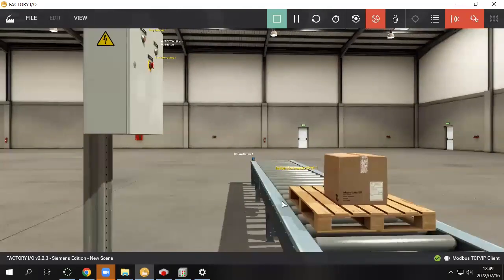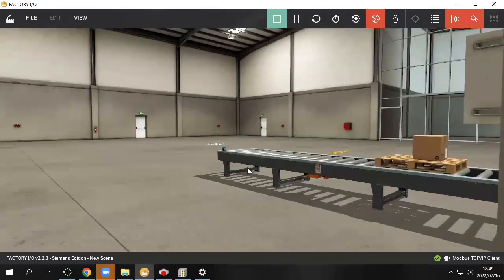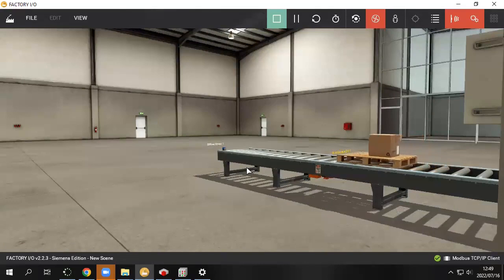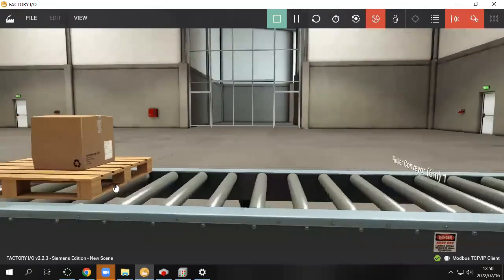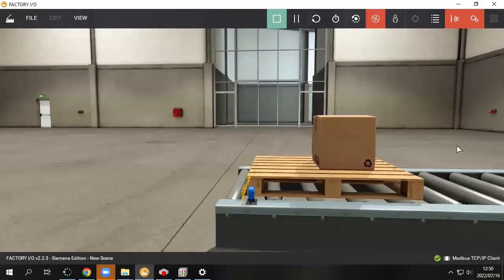Right. So now, at first, what did it do? It fell. So we don't want it to fall. Yeah, this is why we're having this. Yes, stop. So now, it stops immediately. Maybe after a few moments, you then stop the conveyor belt. You then go to your program, re-amend it, put a timer, and it will follow the timer. We can do the timer thing because I believe it's very important.